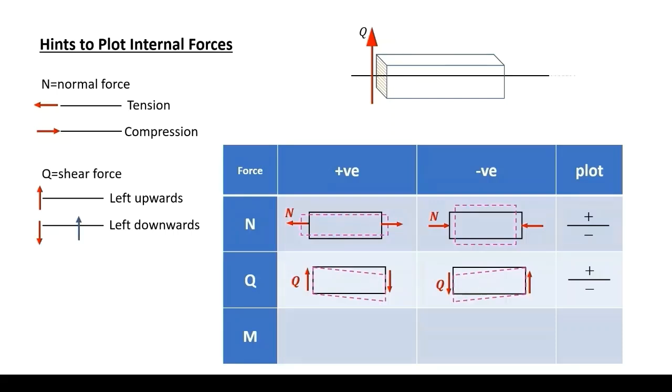Any positive shear opposite to the direction of the negative shear previously computed will be algebraically added to it, decreasing the value of the negative shear, and may even convert the total shear to a positive shear depending on the forces newly applied on the beam.